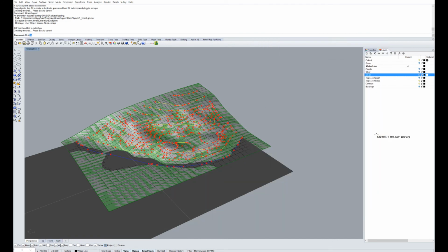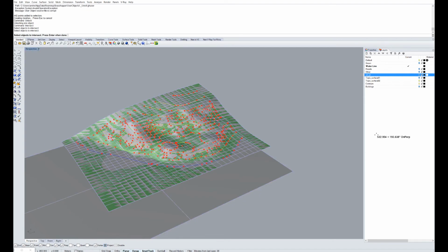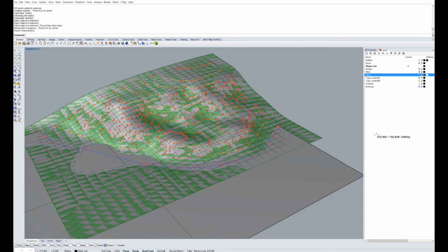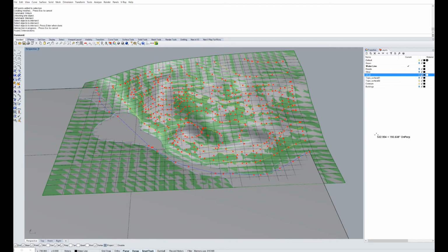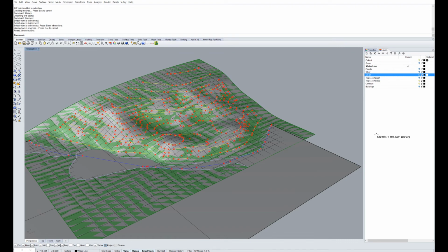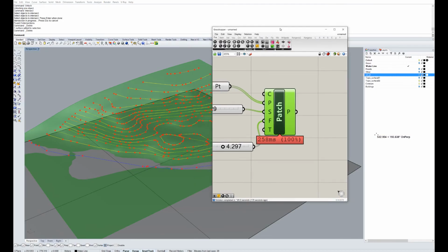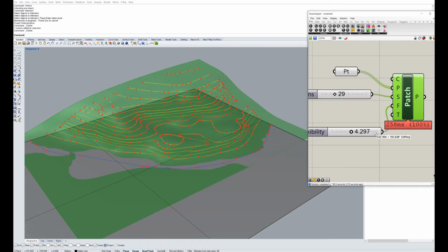So I'm just going to double check this. I'm going to unlock my water and quickly intersect these two surfaces. So I can select this surface, select that surface, quickly intersect the two, and we get a quick idea of how these two surfaces are intersecting. So obviously there is a problem there. So I can delete this, go back to my Grasshopper model, adjust it a little bit.